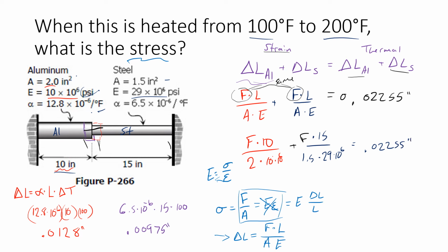We've got just one variable. We can solve this. We simplify this whole fraction and this whole fraction, add like terms together, and F is going to equal 26,700 pounds. That's the unit because it's force, and force is measured in pounds, as we're in English units here. So this is the amount of force on the system. If you had to measure how much the wall is pressing inwards, it would be 26,700 pounds.